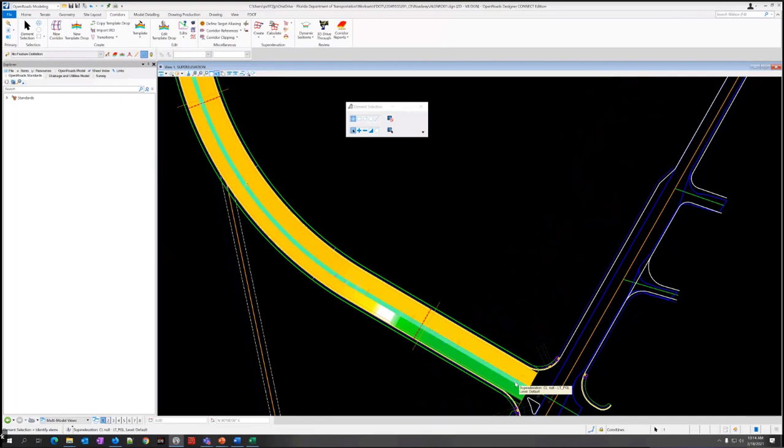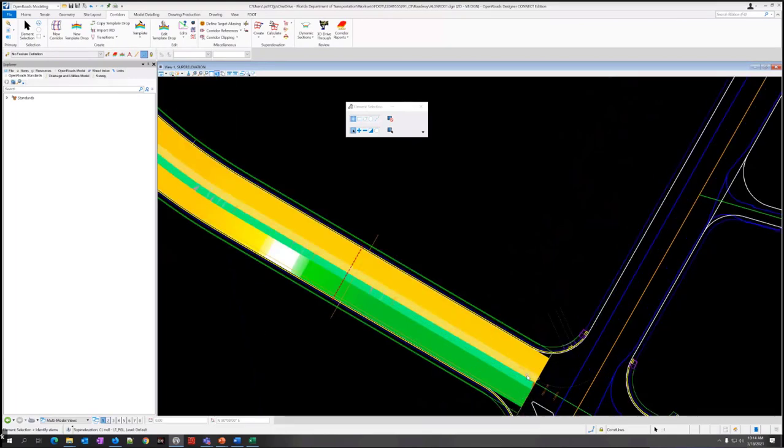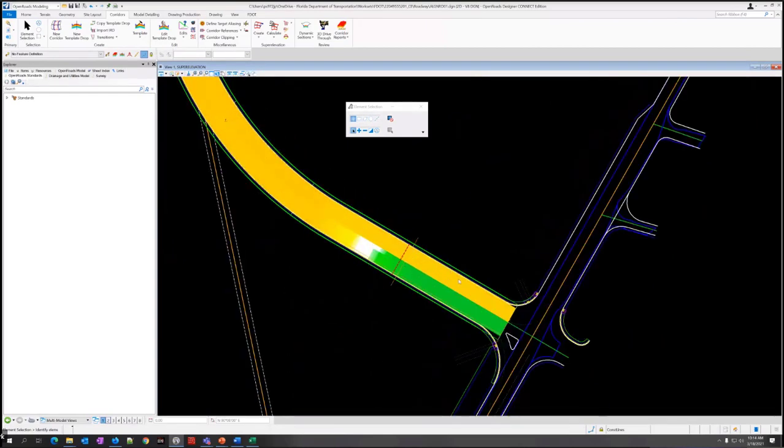If you hover over this, you can see there's a lane here in the median, and there's also some numbers on the handles. You've got a lane on this side of the median, so yellow means it's sloped. In this one, it's sloped down to the right, essentially, in this case. And the green means it's sloped down to the left. So this is a normal crown section over here by the intersection.